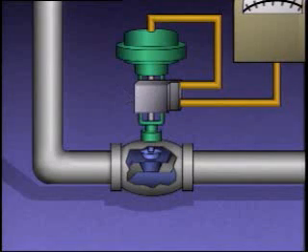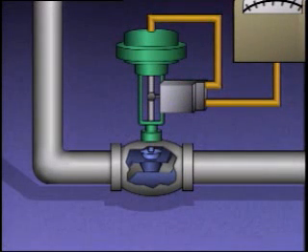If we move the positioner to one side, we can see that a mechanical linkage joins the valve stem to the positioner. This linkage, often called the feedback linkage, indicates the valve's position to the positioner. The output speed from a single-speed motor can be controlled by connecting it to the process through a variable speed coupling. In this case, the coupling acts as the final control element.